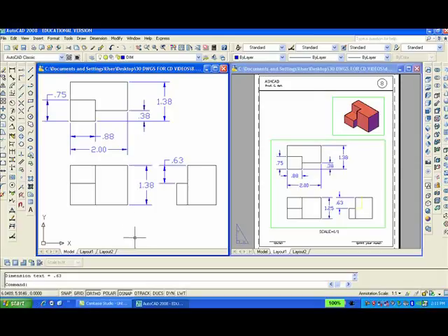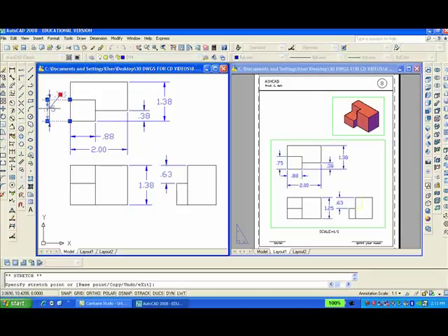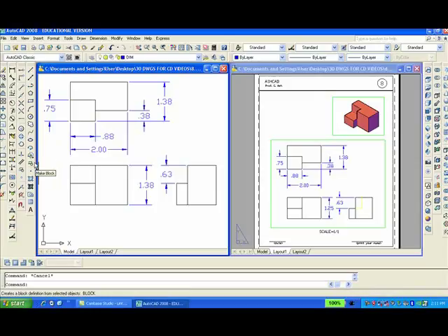And remember that if you want to make those dimensions look better, you take off Object Snap and Ortho, click on the object, the dimension, and just drag it down where you want it, like so. Same thing with this. Hit escape, click on that, drag it down to where you want it, like that. So the 3 views look correct.